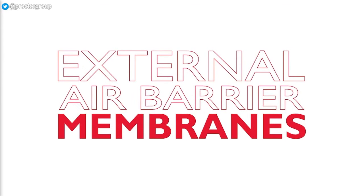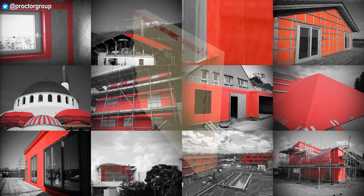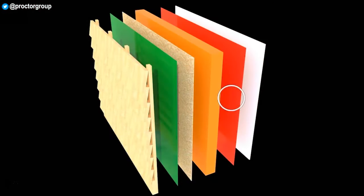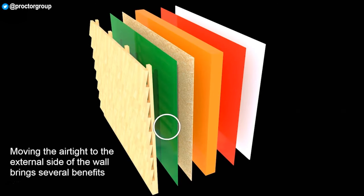External air barrier membranes. One of the more recent construction membrane developments is the use of external air barrier membranes, which represent a significant departure from accepted traditional practice. Traditionally, the vapour control layer, being inherently airtight, has performed the function of the airtight layer in the construction. While this solution does work, it places a lot of emphasis on the quality of installation and sealing of the membrane, which can be difficult and time-consuming. Moving the airtight layer to the outside of the heated envelope presents a faster, simpler and more robust solution.